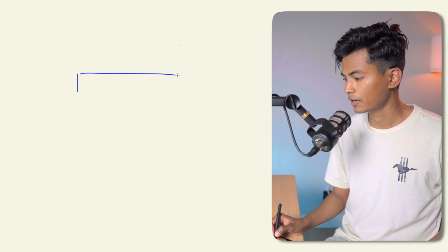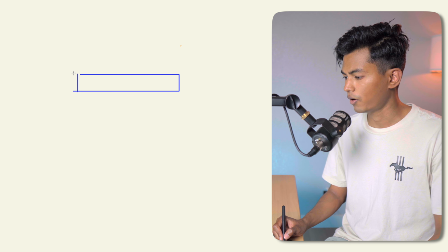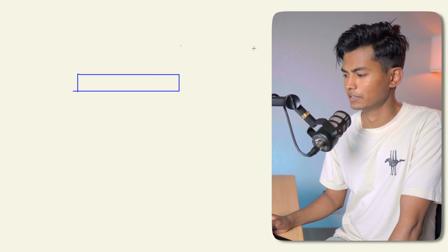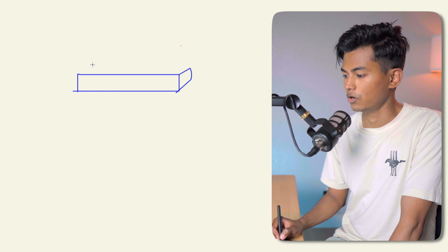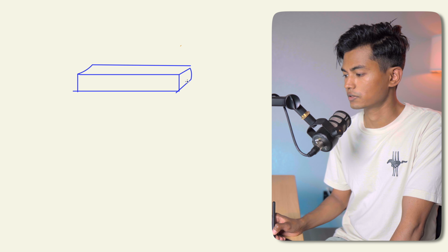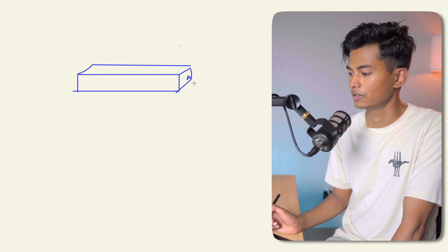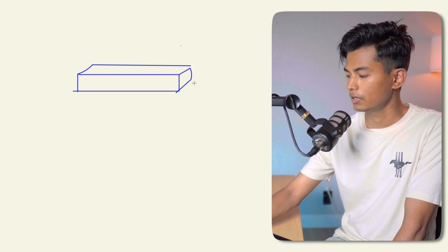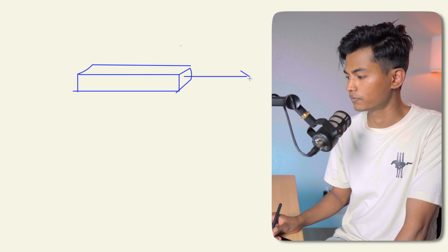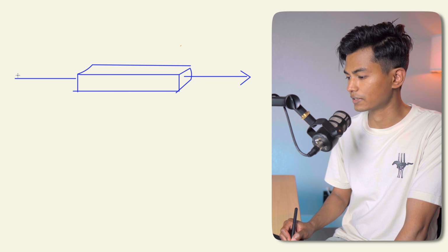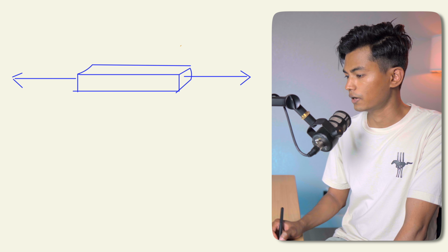So we are considering again a form of body that is called a prismatic body. A prismatic body basically means that the area of cross section remains constant longitudinally. All across, the area is constant, say A. Now it is again going to be applied with a longitudinal load in the x direction, equal and opposite.